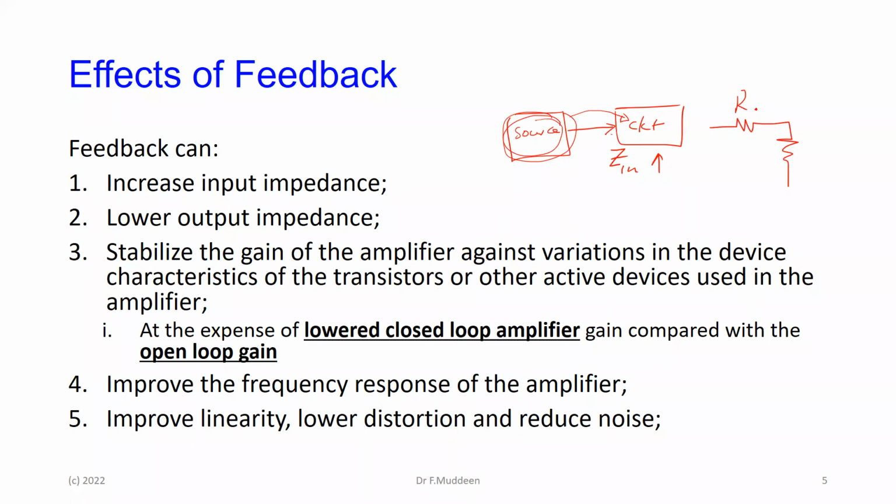If you have two resistors, R1 and R2, and I have some voltage Vn here, if R2 is large compared to R1, most of Vn appears across R2. But if R2 is small compared to R1, most of Vn appears across R1. If this is where you want the useful signal to be propagated and R2 is too small, you get a very small signal. In fact, you load the source. The source is dropping all of its signal inside instead of on the load itself. All right, everybody seeing that? Make some sense?